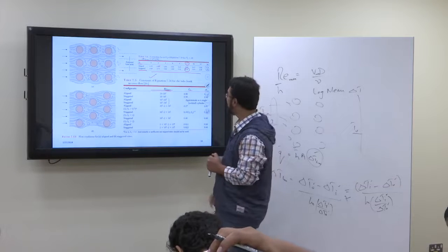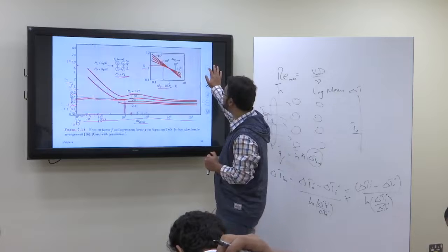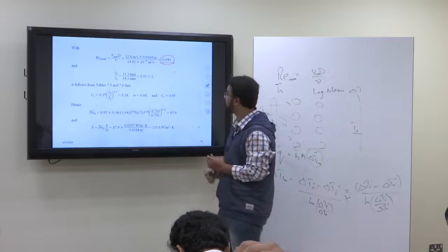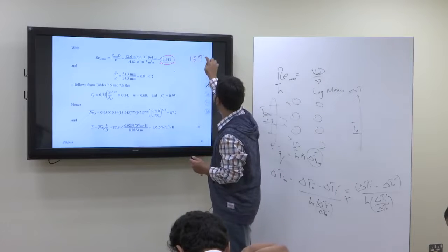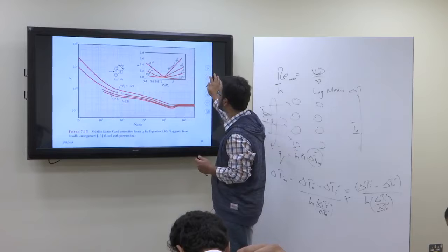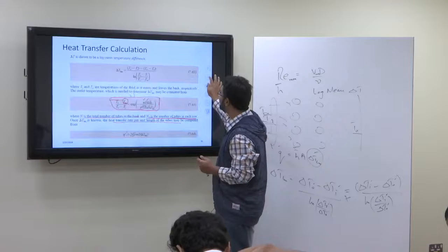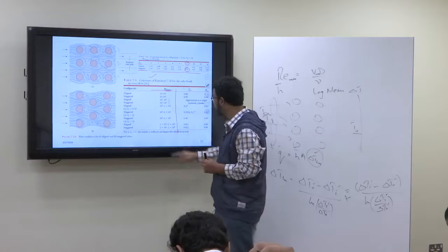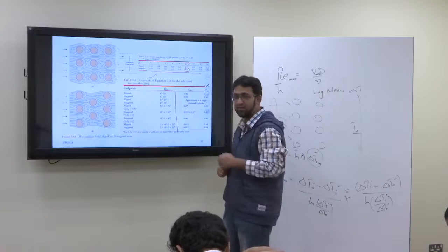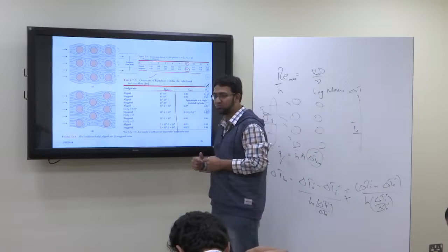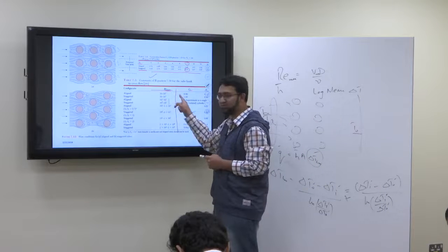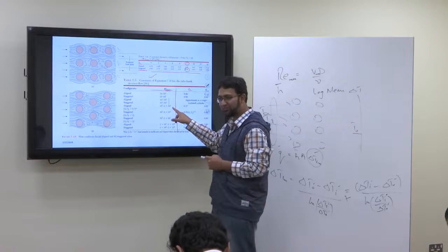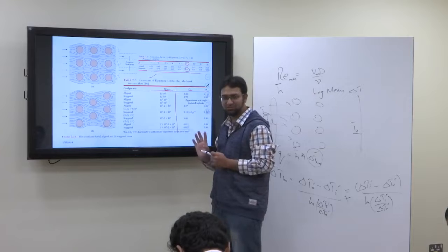Now, what was your Reynolds number? Reynolds max came out to be 13943. So I write it here, 13943, and come back. In which range will it come? 10 to 10 to the power 2? No. 10 to the power 2 to 10 to the power 3? No. 10 to the power 3 to 2 into 10 to the power 5? Yes, within this range it will come.